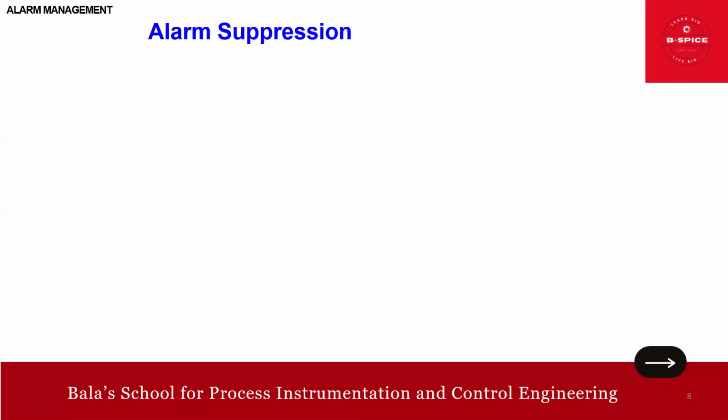Then we go into the logical suppression. Logical suppression, I didn't have any write-up here, but I will explain here. Consider a case, two machines installed, one duty and one standby. You know better, so that's why I didn't put anything, but I'll try to explain. Take a source, machine A stopped and machine B stopped. So the suppression now is stop command A and stop command B.